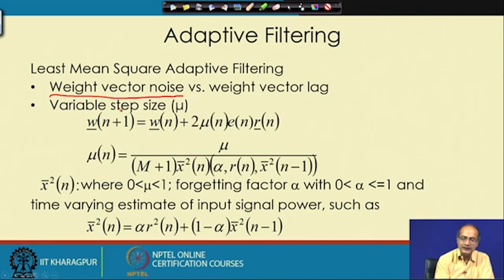That means there is a noisy estimate we are taking for the weight vector, and that is getting reflected in the output as noise. The main source of it is that at the beginning of the LMS algorithm, there was an expectation operator on the error, and we have dropped that. This is the result of removing the expectation operator, or that smoothing operation.